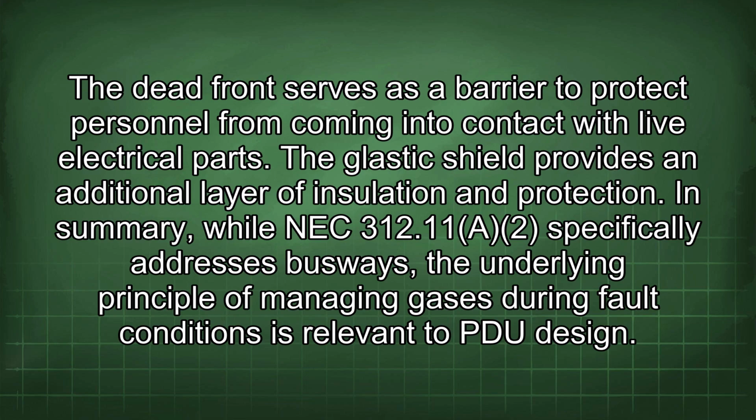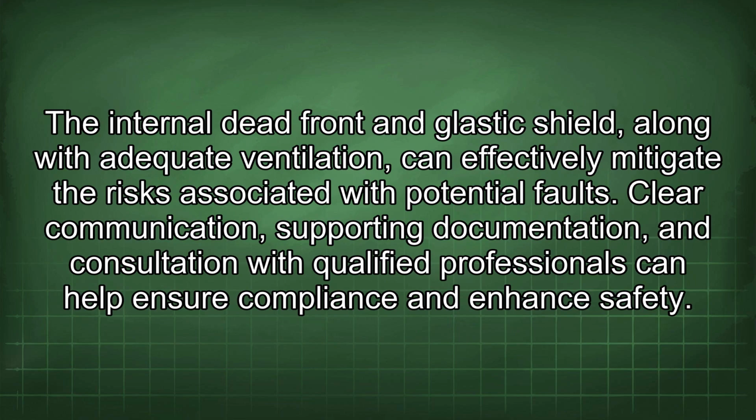In summary, while NEC 312.11(A)(2) specifically addresses busways, the underlying principle of managing gases during fault conditions is relevant to PDU design. The internal dead front and glastic shield, along with adequate ventilation, can effectively mitigate the risks associated with potential faults. Clear communication, supporting documentation, and consultation with qualified professionals could help ensure compliance and enhance safety.